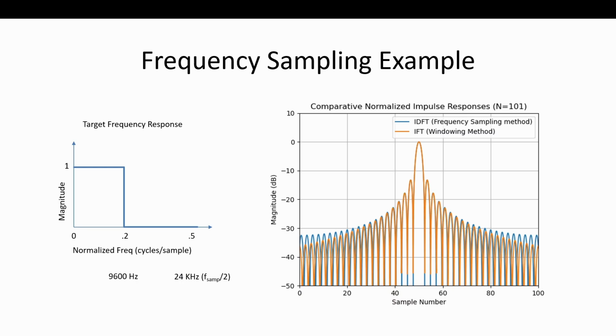At some point, you're down below the don't care point. In this case, you get your impulse response because it's a sinc. We know it's a sinc. Just use the formula, get the samples of the sinc. But what if this was some arbitrary shape? I'll show you that in the notebook. What if we're doing some weird, wild shape and you want to match a filter to have this arbitrary phase and magnitude? This is a great approach for that because it's your fast path to getting the impulse response. Just oversample it to minimize the time domain aliasing.